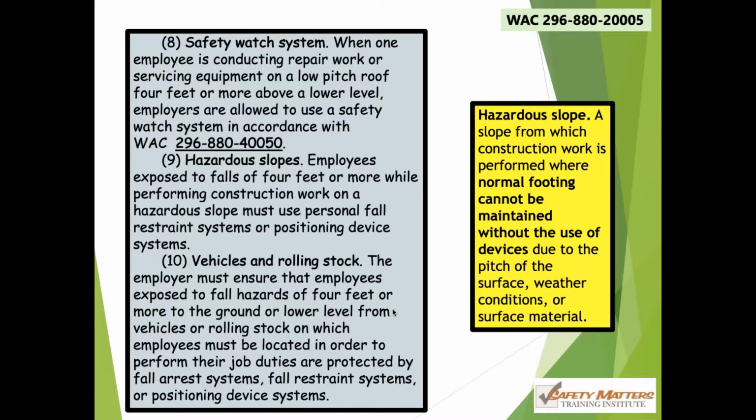You can use a safety watch system when one employee is conducting repair work or servicing equipment on a low-pitched roof, 4 feet or more. You could use the safety watch. It's a 1-to-1 system. This is what a hazardous slope is. Anybody working more than 4 feet on a hazardous slope, a slope from which construction work is performed where normal footing cannot be maintained without the use of devices due to the pitch, the weather conditions, or the other surface materials. We have to protect these guys at 4 feet.